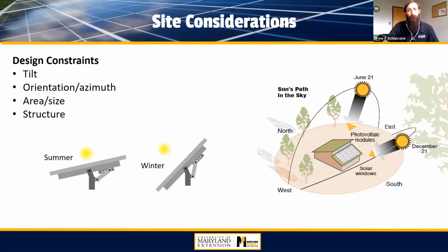If you want to go back and review some of those details, you're welcome to do so. The area and the size of the system, if you're building a really large system: is your roof going to support it structurally? Do you have the space on your roof to hold that? And it's not only the exact size of your roof, but depending on your jurisdiction, you'll have fire codes and spacing requirements that you'll have to meet. You'll have chimneys and pipes to work around. So you don't necessarily assume that you have your entire roof structure.